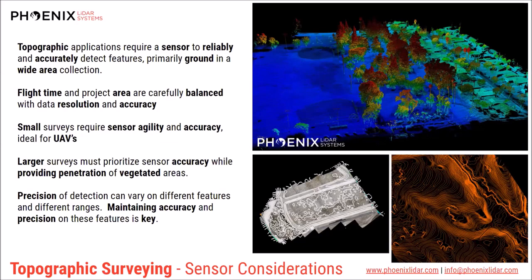So if you're deciding on a VUX-1LR that you're going to be flying from 500 meters, that's not a great option if you also need to have it colored by a very small, low resolution camera. Those two hardwares don't work well together. So making sure that you have a good idea of that, or at least know how these different hardwares factor into each other, is key.